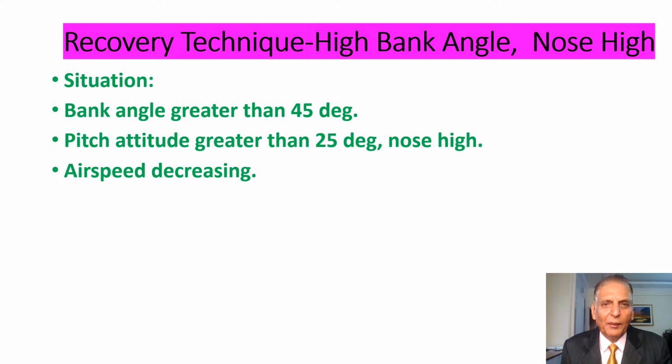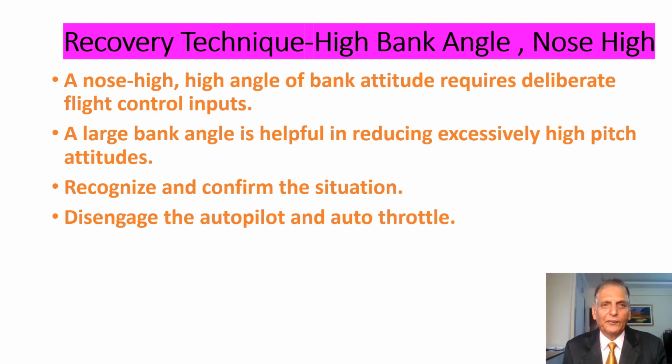Situation: bank angle greater than 45 degrees, pitch attitude greater than 25 degrees nose high, airspeed decreasing. A nose high angle of bank attitude requires deliberate flight control inputs. A large bank angle is useful in reducing excessively high pitch attitudes.